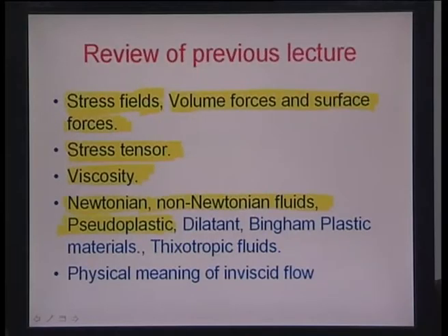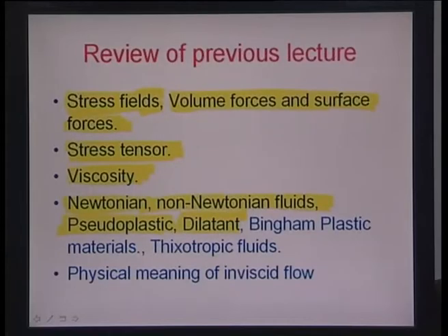Then we talked about various kinds of non-Newtonian fluids like pseudoplastics, wherein the viscosity seems to go down with the deformation rate. Dilatant, where the viscosity has a reverse behavior, going up with the deformation rate. And then Bingham plastics, which essentially behave as a solid up to a certain yield stress, beyond which they follow the path of a Newtonian fluid.